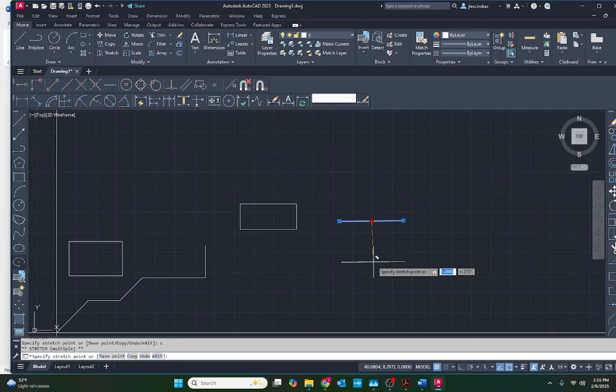So in this case, if I'm copying this, I may want to make a copy that's exactly 1 inch away. So I would type 1 inch down. I would type @ 0 because I don't want it to change in the x direction, and then I want it to move by 1 unit. So comma -1, and that moved it down by 1. And it still leaves me in the copy mode in case I want to place more of these. So that's how copy works, along with select.